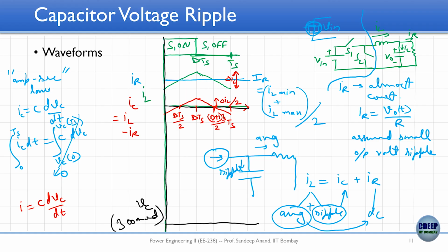So I am just assigning all these 4 instances appropriate timing instants, right. Is that okay? So midpoint is dTs of course, and the midpoint between 0 to dTs is dTs by 2, which is where the current is crossing 0, and then again current is crossing 0 at 1 plus d times Ts by 2.